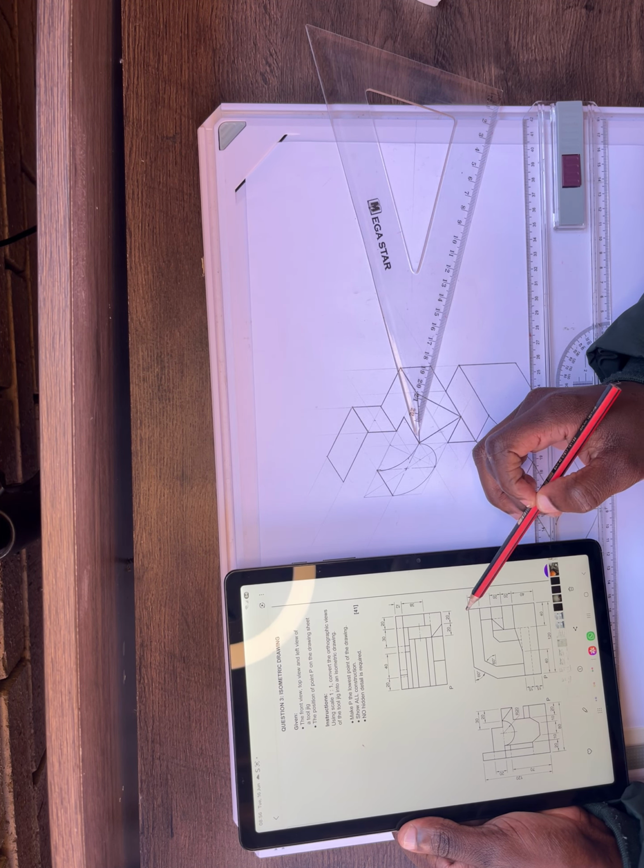So if you are aware, I'm ignoring these. Why? Because it's non-isometric lines. If I cannot draw it by joining 2 isometric lines, it means that I have to construct it. But now I want to start by drawing all the isometric lines that are there before I can join this one. So now this line from here going up is 20, which means I will start from here, then I go up at 20.